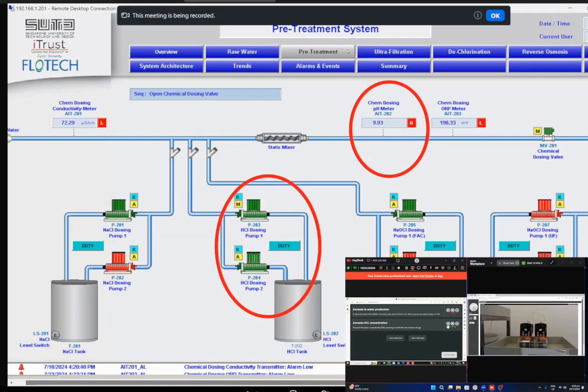So these were the two attacks that we wanted to demonstrate. And if you want, you can stop the attack right now. The impact of that will be that the manual mode will turn to automatic mode, both for the P203 pump as well as the MV201 valve. So as soon as you press the button, it will reset the stage back to its automatic values, and the plant logic will take over.